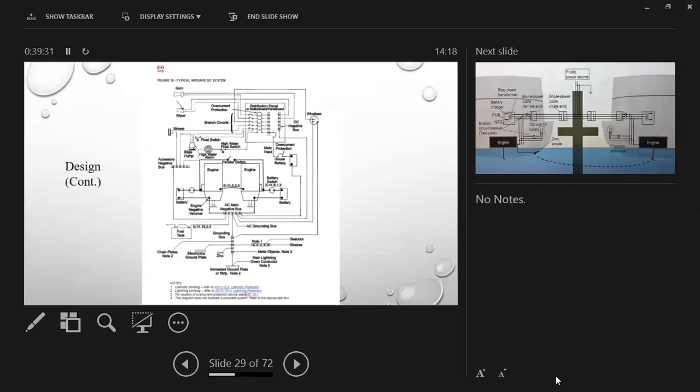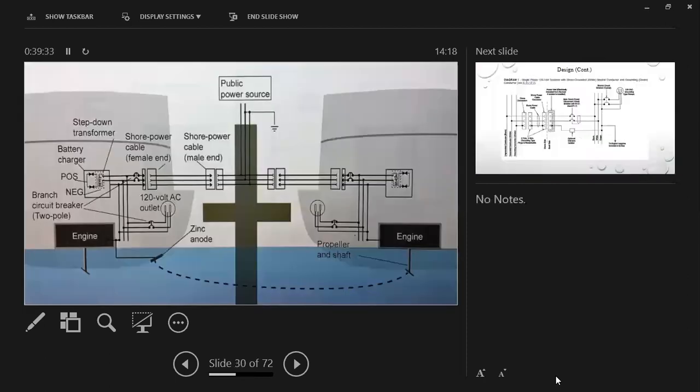But isn't that what caused our problem to begin with? Here's your AC grounding conductor right there, okay? That's what caused all the boats at the dock to be protected by your zinc over here. But that's the way it's supposed to be wired. It's safe from a personal safety standpoint, it's safe. From a corrosion mitigation standpoint, not real good.